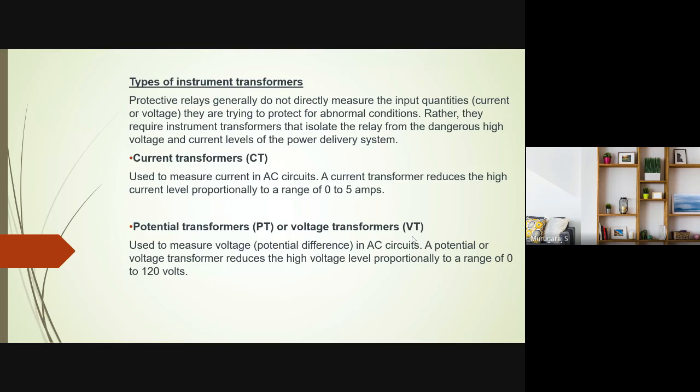Not only a motor, a transformer also takes more starting current, because when there is no EMF in the secondary side, the primary side tends to take more starting current. It will be in the range of 7 times the rated current. Suppose a 10 kilowatt motor takes 10 amps, the short circuit current will be in the range of 70 amps or 80 amps. Actually, it is allowed as per IEC, subject to IS tolerance for the motors.